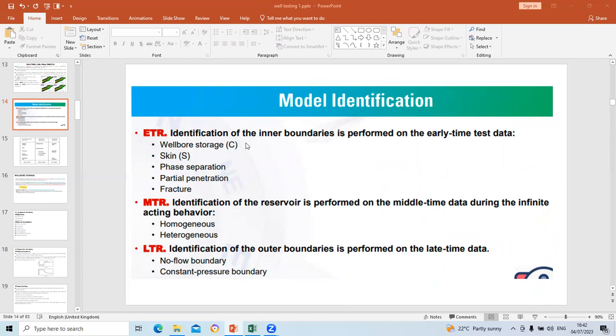We can calculate the wellbore storage. The wellbore storage is the amount of fluid that is already inside the wellbore before production. So it may be, for example, a drawdown test, because there are two types of tests. We have a drawdown test where the well is shut in for a period of time, then it is allowed to reach static condition. Static condition is a condition where there is no pressure gradient. Fluid cannot flow into the reservoir. At that point in time, now drawdown starts.